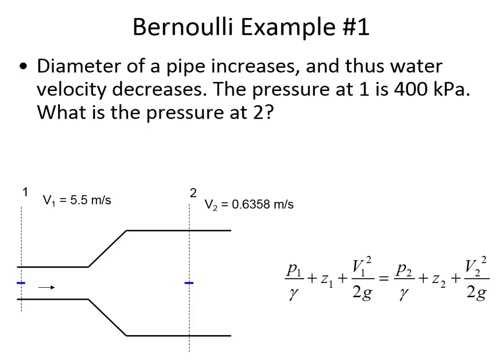There would be a little bit of extra energy loss because of that viscosity. The viscosity, what does it do? It causes energy losses. So you wouldn't expect the pressure to be higher than this. This is a maximum. But the viscosity assumption that we're sort of violating a little bit causes energy losses that would be observed by a reduced pressure.